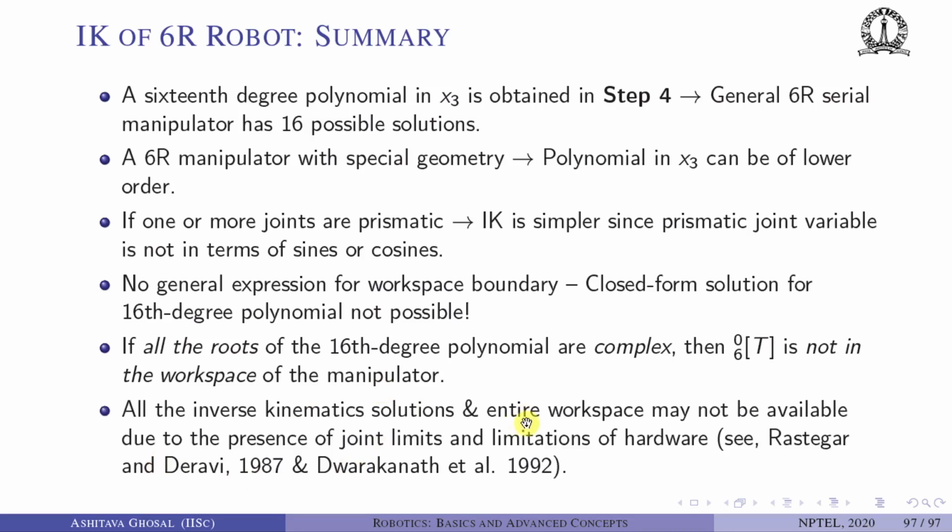All the inverse kinematic solutions and entire workspace may not be available due to joint limits and limitations of hardware. This is also a very important concept. Till now, we have not assumed that there are joint limits. In an actual robot, you cannot move the joint beyond certain limits. So if you want to consider the joint limits, then the workspace is further reduced.